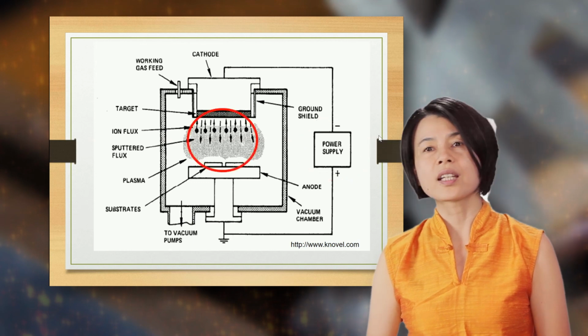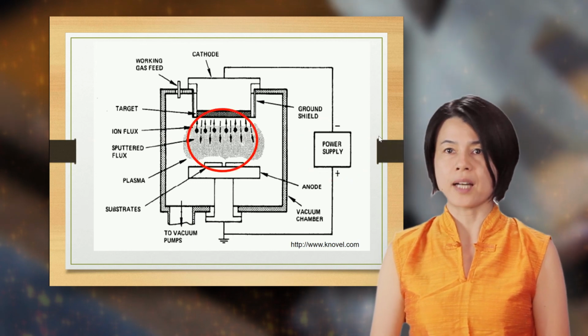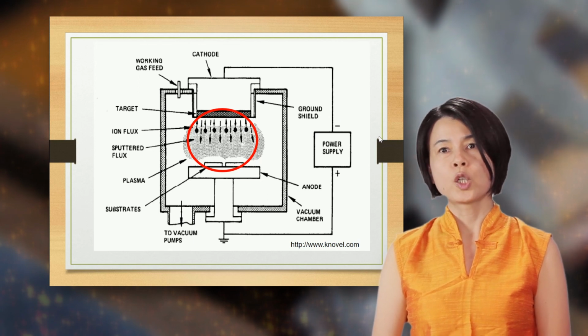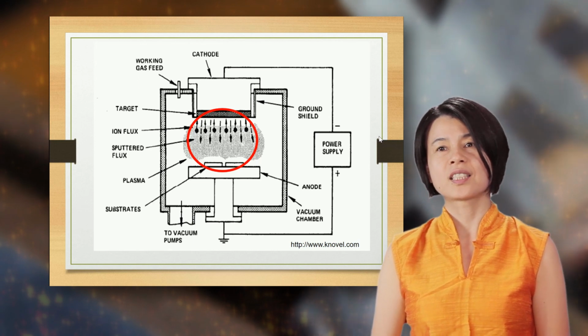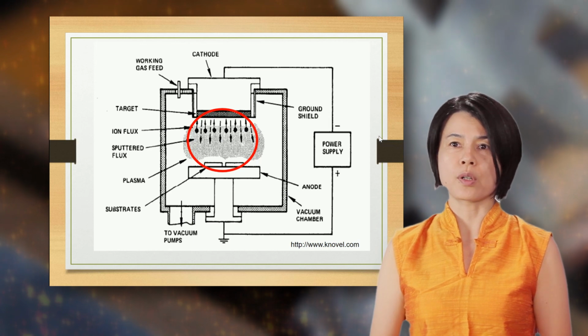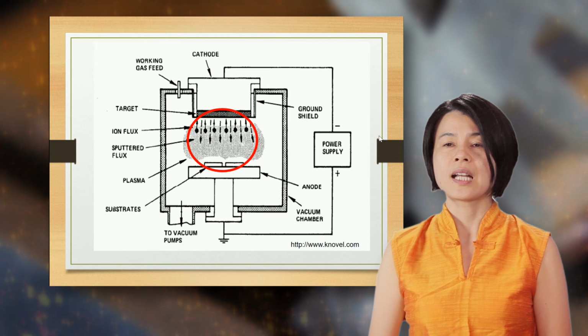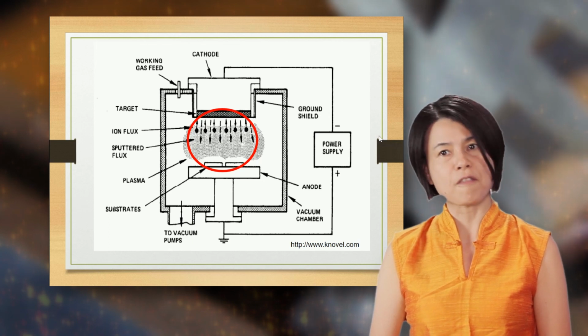Next, the target is at the top while the wafer is at the bottom. Target material is expelled by the power supply to reach the plasma state. The high energy target material in the plasma state bombards the wafer at the bottom and is deposited as a thin film.